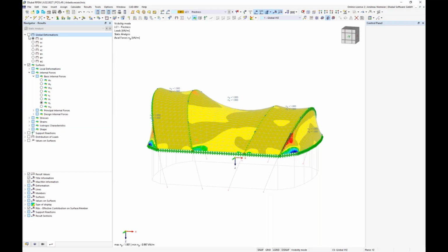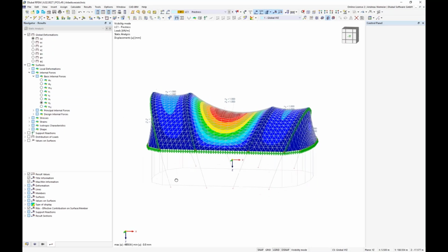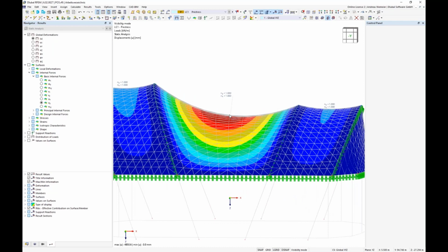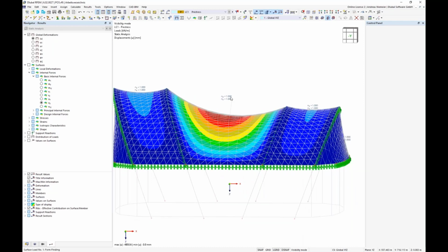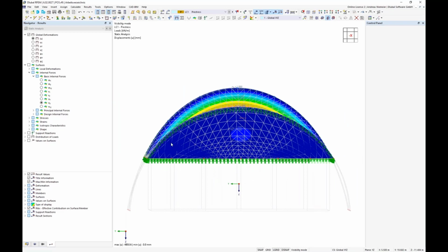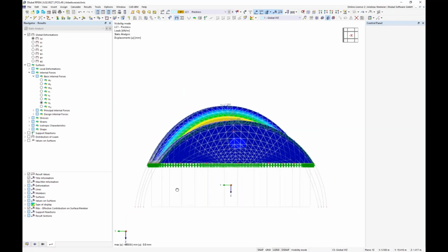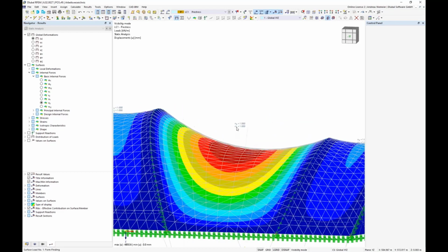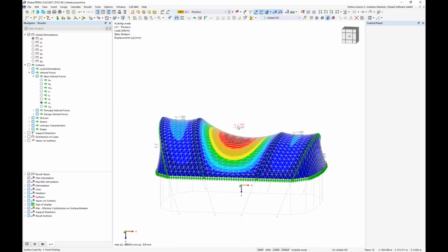But the only unnice thing is that we have here a really big sag, and I want to lift it a little bit so that we don't have such a big sag here. And to reduce this sag, we have to reduce this tangential pre-stress direction. For this, we should change one figure here, but I don't know what is y and x at the moment. We have to specify it.